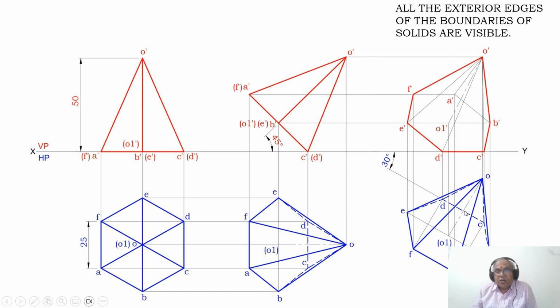From C, you cut an arc on that CD line. Then from this point, with reference to CD, you measure an angle of 90 degrees with respect to CD and draw a perpendicular. Then from this point to O, you measure the distance. Transfer it from this point to that point on that line, O. From O, you measure the distance of O to O1. From O, you cut an arc on this perpendicular line. So you get O1; you mark that point.